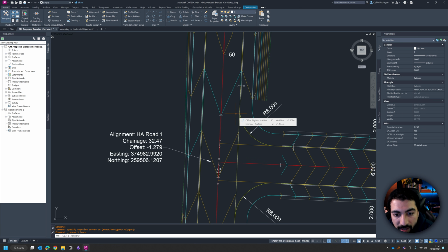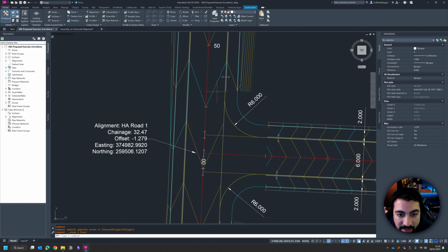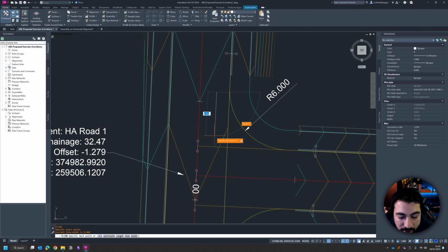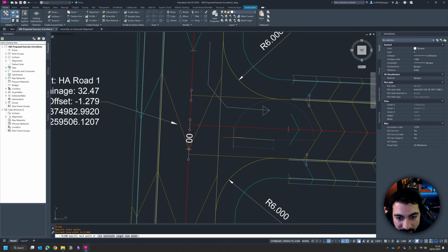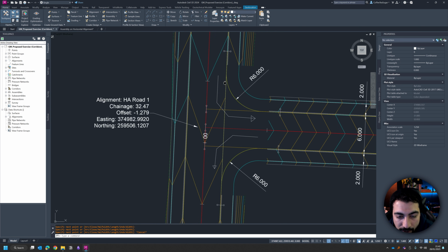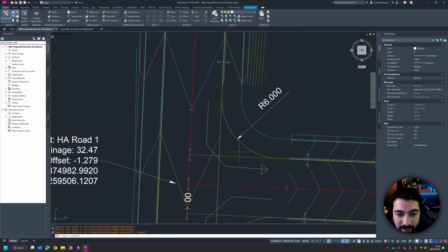The rule of thumb that I always suggest to whoever I teach to create a junction is: entry junction, exit junction. So when you're entering the junction and when you're exiting the junction. Always start with how you enter the junction. Let's draw this just to remind myself that that's how I'm entering, and let me draw this just to remind that that's how I'm exiting the junction. With that being said, I'm going to create now my connected alignment.